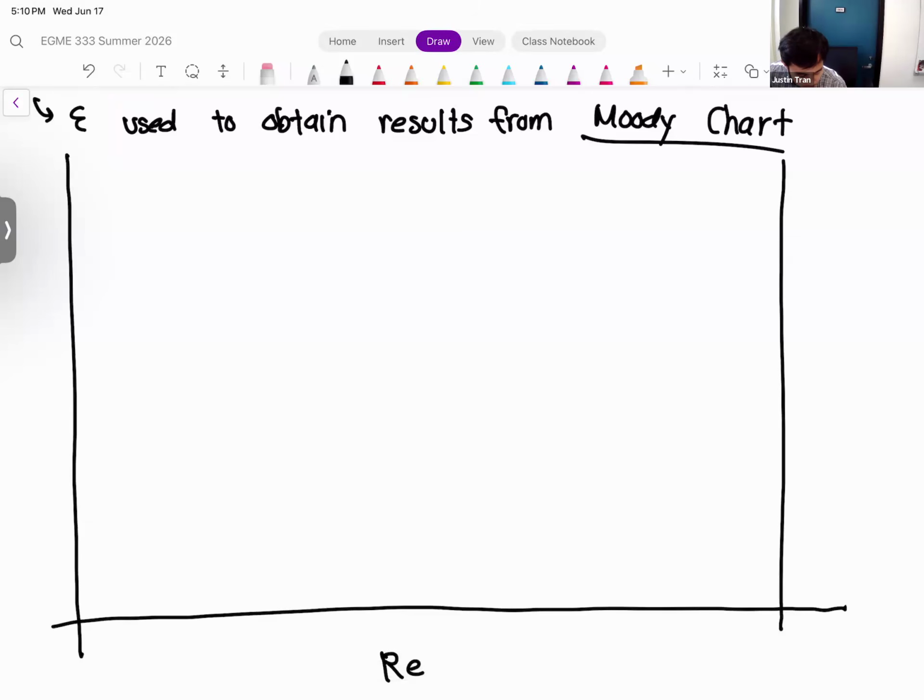And you want to be careful using this because the Reynolds number on the horizontal axis uses a log scale here, right? And so instead of being a linear scale, it's scaled logarithmically. So that means each tick mark goes up by an order of magnitude: 10 to the 3rd, 10 to the 4th, 10 to the 5th, 10 to the 6th, 10 to the 7th, okay? It even goes all the way up to 10 to the 8th, so that is super turbulent flow, okay? Which does exist, right? A Reynolds number of 10 to the 8th sounds very large, but those types of systems do exist.